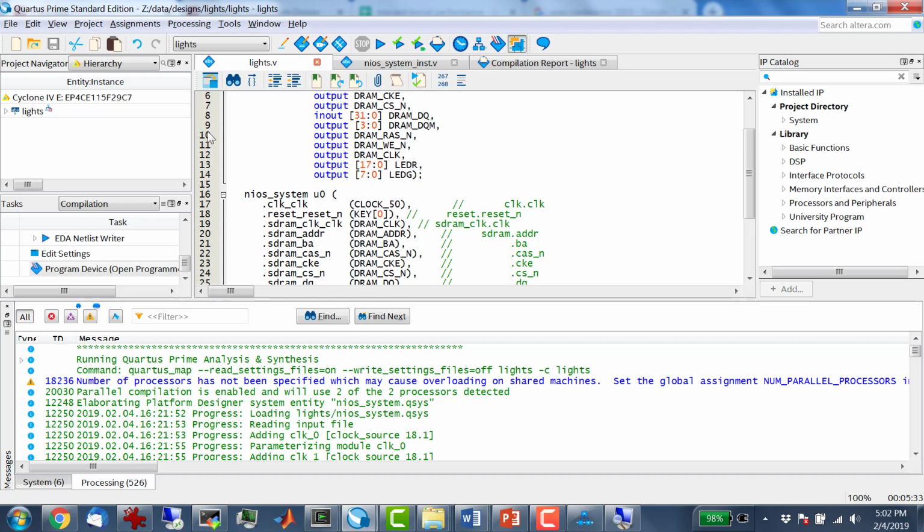Yeah, you could connect the interrupt. There's an interrupt pin that comes from the buttons. I don't do that. That's up to you if you want to try it. The other option would be to not have it sleep for the whole amount. Instead of sleeping for a quarter of a second, you could have it sleep in 20th-of-a-second increments or something like that, and then in between you could check the button. So you could fix that problem in the code, but a lot of times groups in this class will get frustrated, like why is this thing so unresponsive, right? That's why. It's a limitation of the software, and that's something you could fix in the software if you wanted to add that feature, but it's not required.